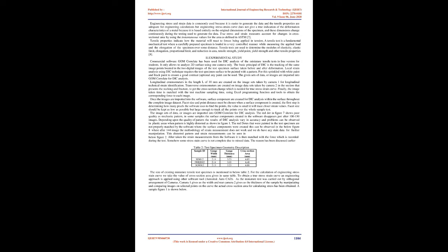One of the most important properties of any material is the measure of its strength. Strength of material can be expressed in many categories: compression, tension, flexure, etc. However, the tensile test provides a lot of information about the strength and mechanical behavior of a material. The basic idea of a tensile test is to place the sample between 2 grips and make sure these grips are fixed. The material sample has some known geometrical features which are the standard ones. Load is applied in such a way that one end remains fixed and load increases on the other end. Keep increasing the load till fracture and meanwhile measure the change in length with respect to original length.